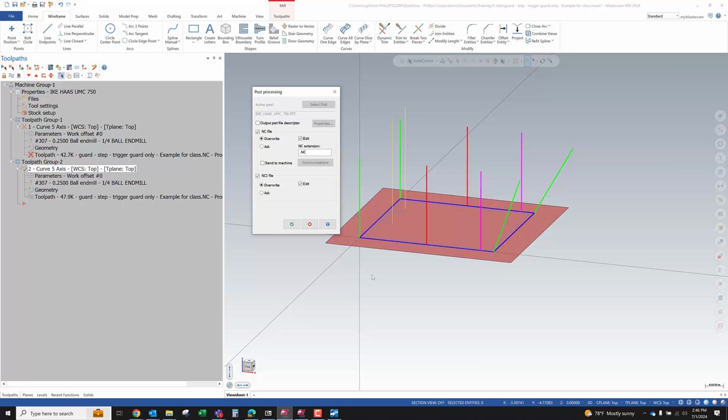And so we could put a negative 1.28 or vice versa. If it was a negative, we could put a positive value in the work offset table for the C-axis. And dynamic work offset will be able to work with that offset in the C-axis and compensate for it. This is not true for the B-axis.